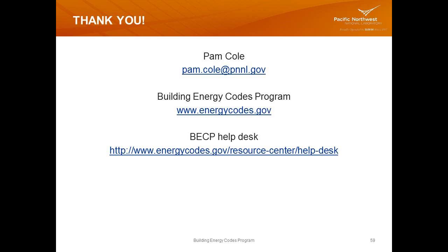Another question is, if an owner adds, for example, a bedroom, is compliance with REScheck required? Yes. So if I'm adding conditioned space to an already existing house, such as a bedroom or a family room, that's considered an addition. And whether you use REScheck or another method, if within your location you have to show compliance to the energy code, you're going to be submitting something for documentation. So if REScheck can be used, I would use REScheck, because it's an easy way to create a compliance report that you could submit to the building department.